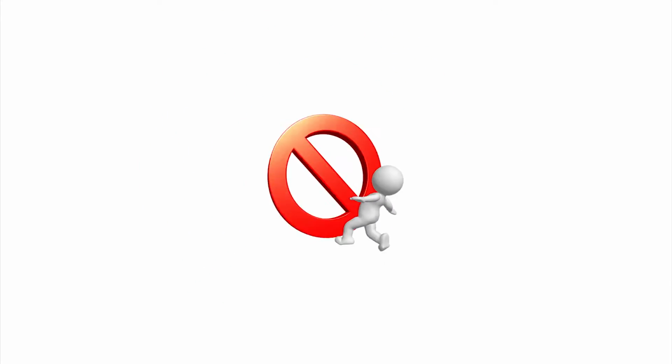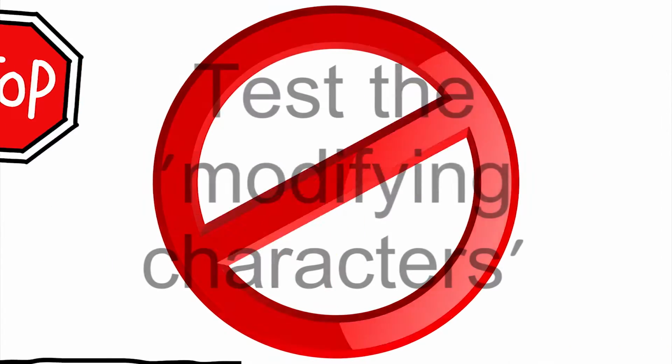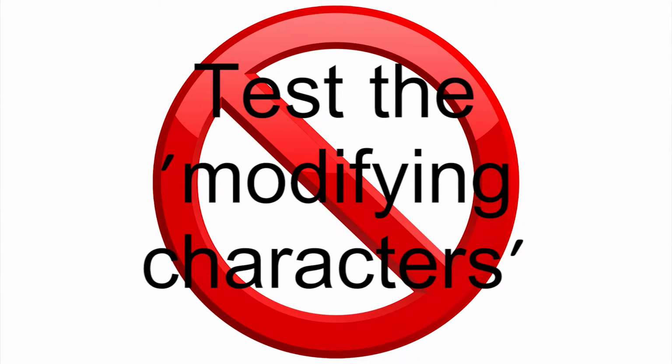Stop the video now and try replacing this with other modifying characters, a star, a percent sign, hash, or an exclamation mark, to see what effect this has on each primitive. Don't forget to press F5 each time to see the effect take place.